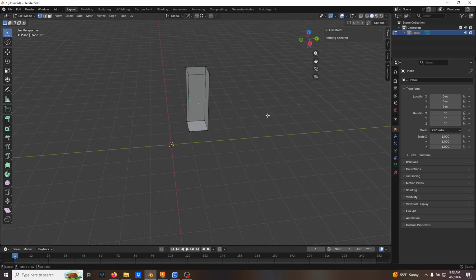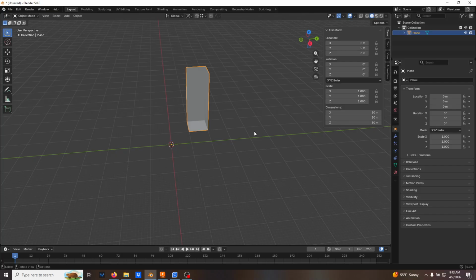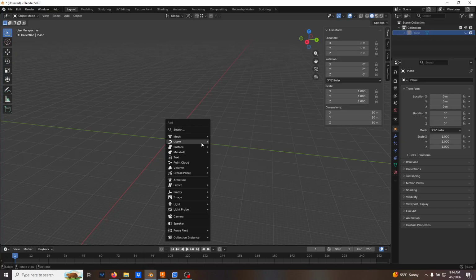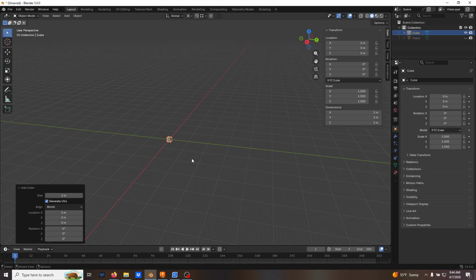So now, whereas I've been using meshes and doing edge operations and vertex operations on them, what I'm going to do here is create an entirely separate object. So we'll leave this right here for right now, and I'm going to hide that to get it out of the way. Then I'll press Shift A and insert another cube, and I'll have my size down here, and I'll just make my size 30.